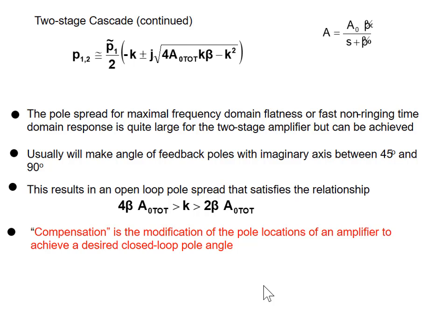Unfortunately, or surprisingly, those are relatively unpopular. A lot of people that use discrete component amplifiers just bite the bullet and spend the extra power and use an amplifier that works with a gain of 1 when they have a higher gain on it.